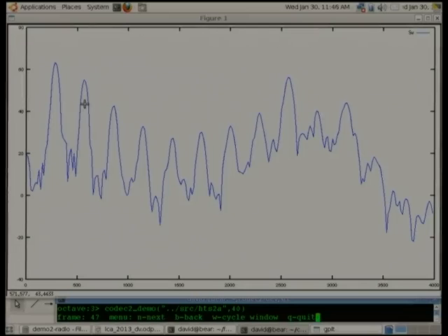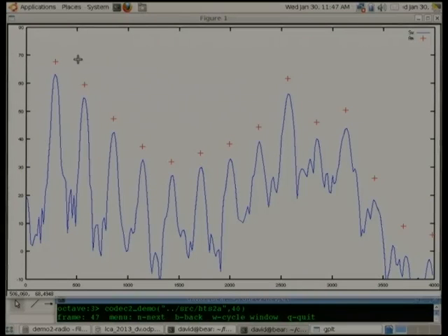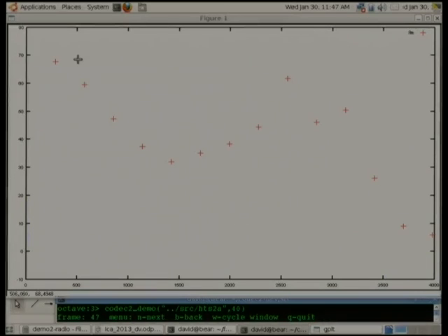It turns out the other thing that's really important for speech perception is where the peaks in the spectrum are. So we have a bit of a peak around here, and we have another one around here. And it turns out that the ear listens for where those peaks are, and that's how we understand what's being said. So the other piece of information that's really important is just the height of all these peaks, or the amplitudes. So we can extract those as a sample, one sample for each of the harmonics of the speech, and then we can really pretty much throw everything else away, and that's what we're left with. So the amplitude of each harmonic and the spacing between them, which is the pitch.